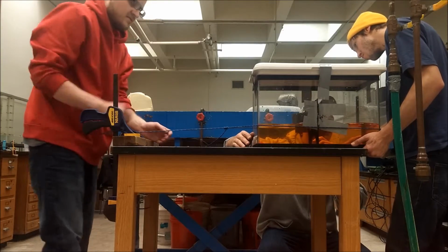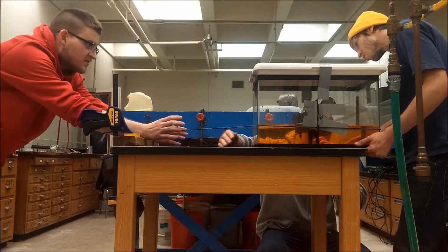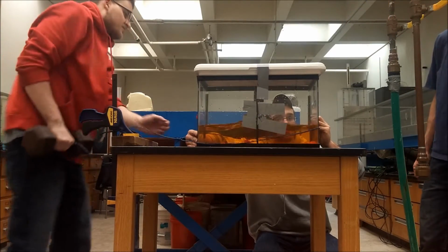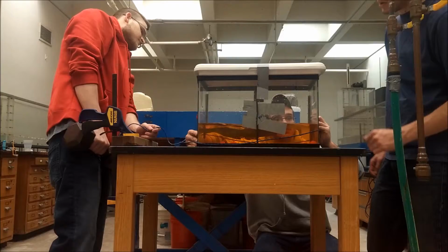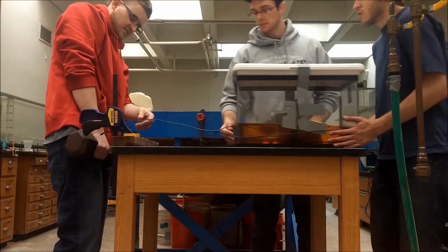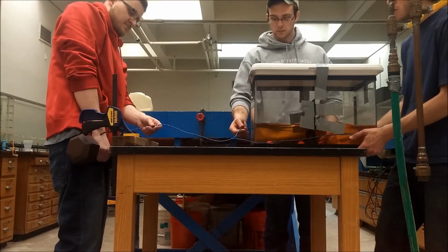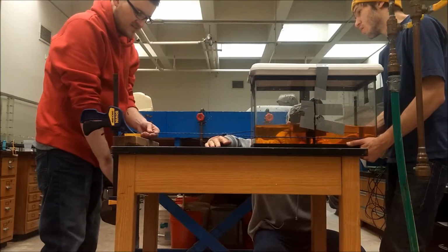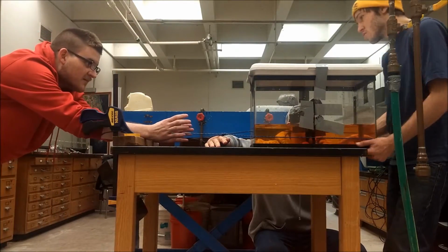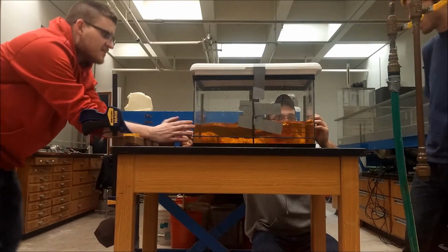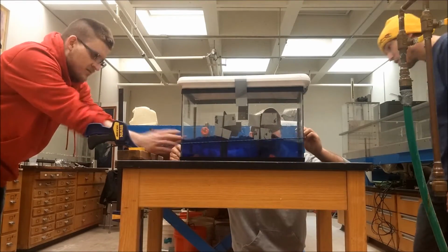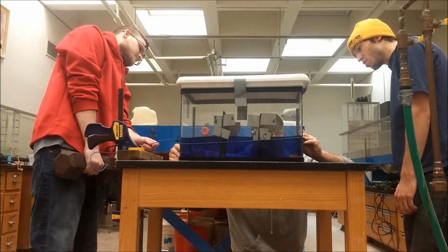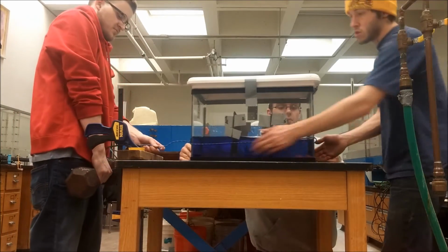The average height the water reaches when no baffles are used was 6.1 centimeters. When only one baffle is used, the water reaches 5.1 centimeters, and when two baffles are used, the water reaches 4.3 centimeters. Therefore, it can be concluded that the more baffles that were used, the lower the height the water reached under constant acceleration. This is because as the dy decreases, dz in effect decreases as well. This was emphasized earlier in the video when discussing the theory behind linear acceleration.